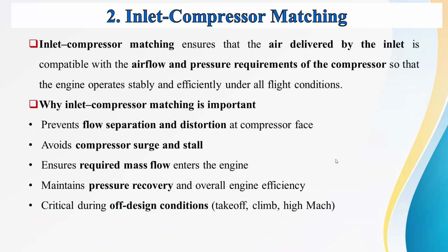So the next topic is inlet compressor matching. Inlet compressor matching is our main topic here. Inlet compressor matching ensures that the air delivered by the inlet is compatible with the air flow and pressure requirements of the compressor, so that the engine operates stable and efficient under all flight conditions. That is the requirement. So inlet and compressor are adjacent components. They have to match each other in order to deliver compatible flow.